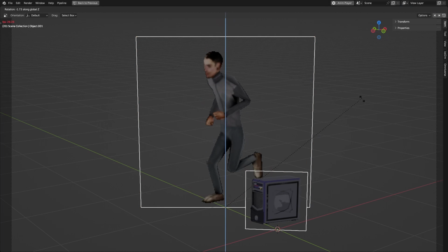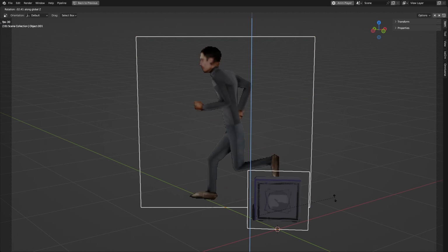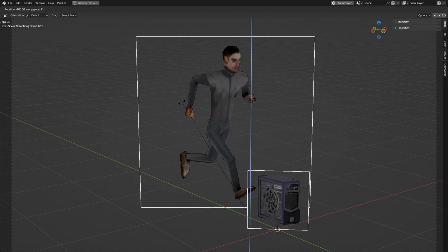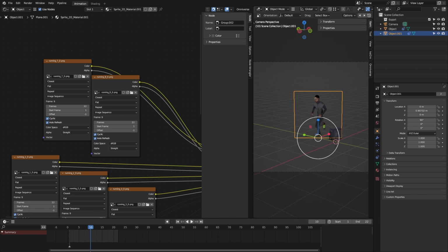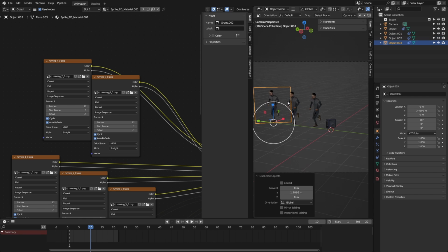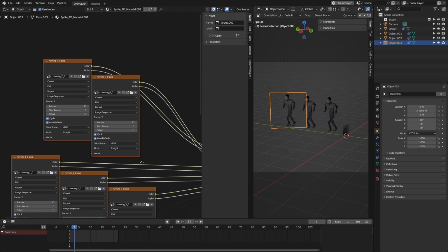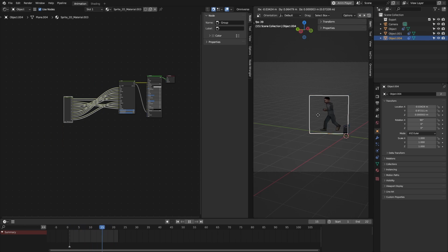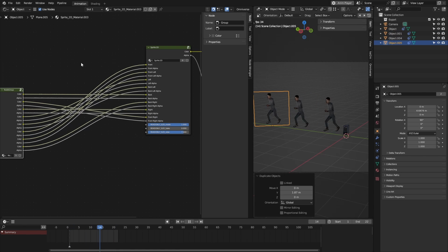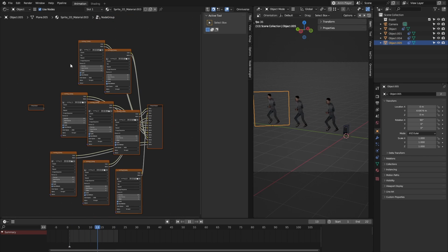You can also rotate or animate the rotation of the object to change its rotation. If you want to have duplicates of a sprite in your scene, be aware that the script will always force these materials to be unique. That means that changing one won't change all of them. So you want to group your input nodes together. That way, after you duplicate your sprite, you still have the ability to control all of them at once.